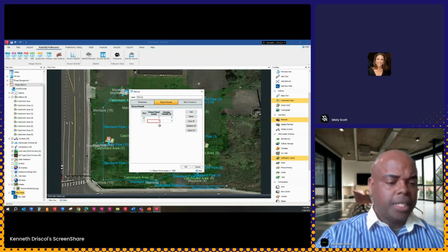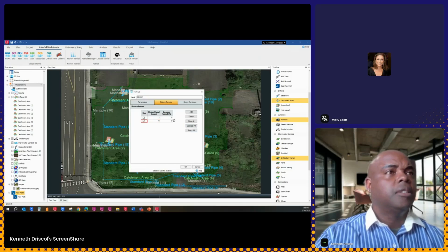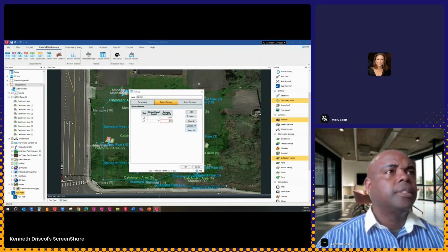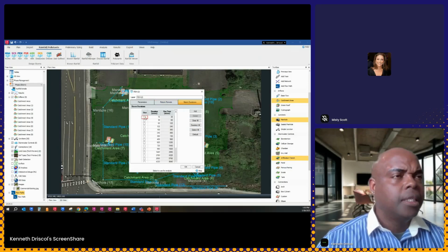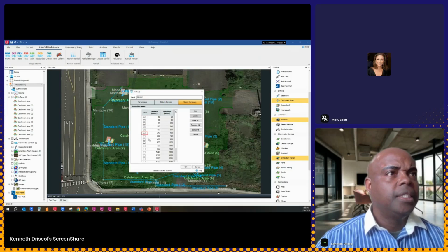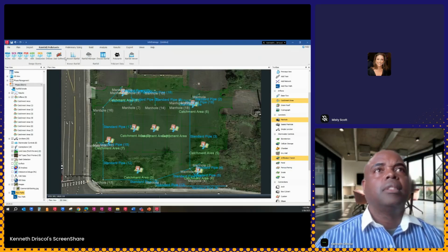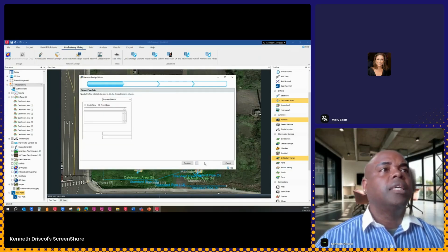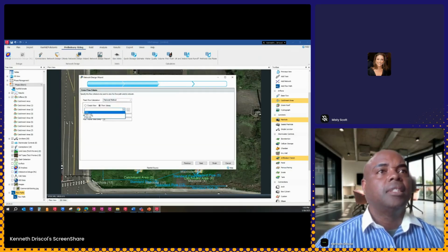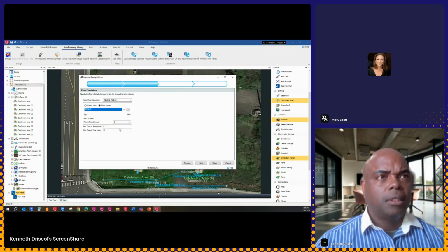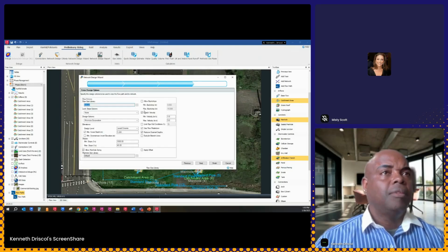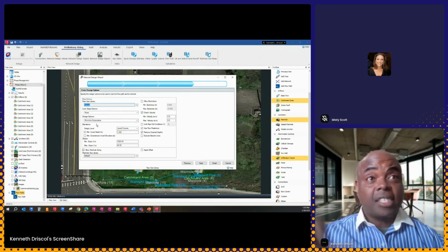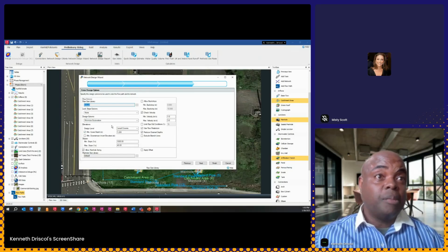A 2-year, we'll add a 10-year. I'll make this simple and say 2%. Storm duration, we'll say 15, 20. Network design wizard. Then we can tell it minimum, maximum, grade, elevation, slopes, whether we want something to change, manhole size.